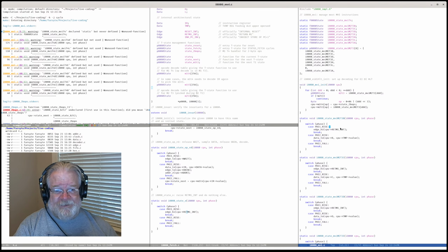So we arrive in these guys with the DB-in signal asserted. And on Phi2 rise, we can now data into our register, but it's not the temp register. These guys are coming from the data bus.